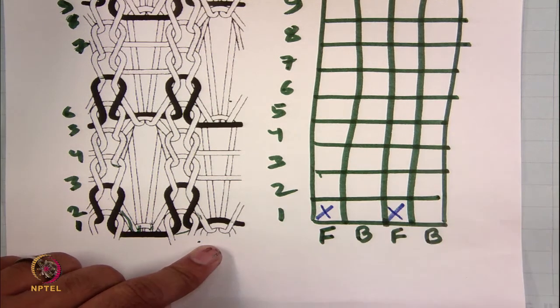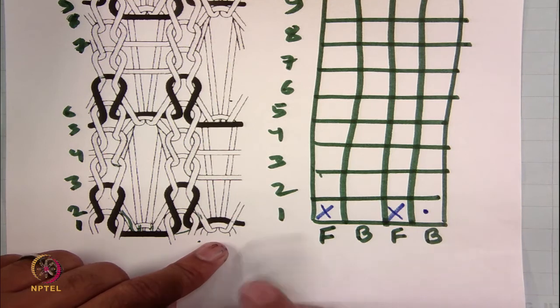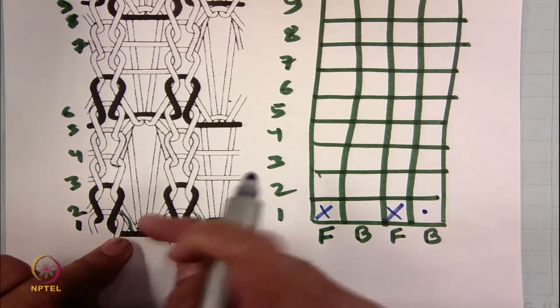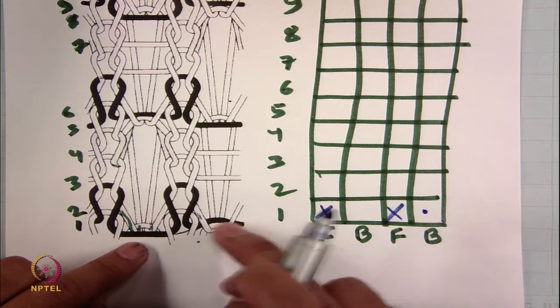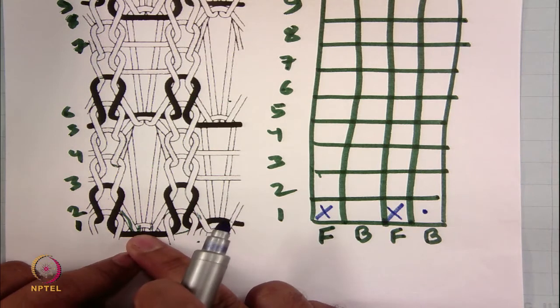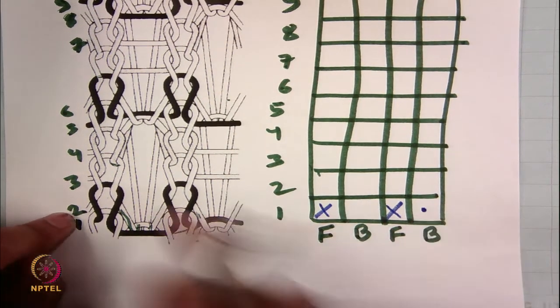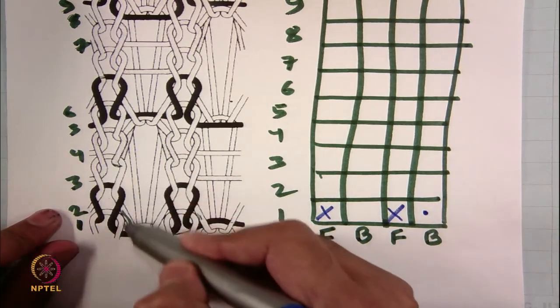So, basically it is holding a 2-yarn loop. So, this is naturally a kind of tuck. Okay. So, cross, float. Here you can see this is a straight part, it is not engaging with the head, but here it is with the head. So, one is tuck, one is float. So, float, tuck.